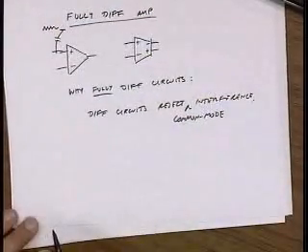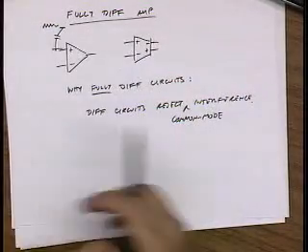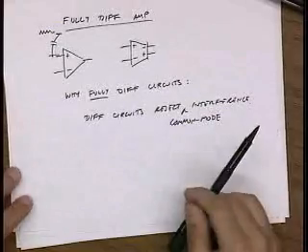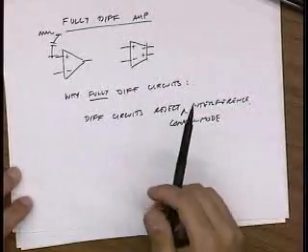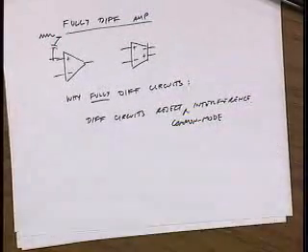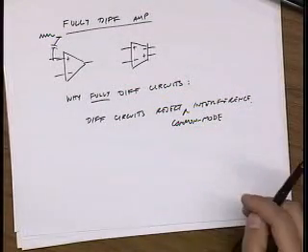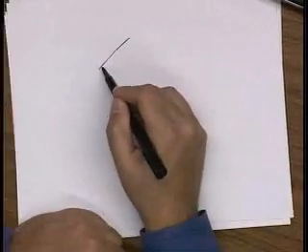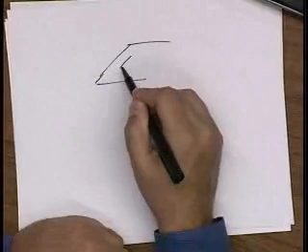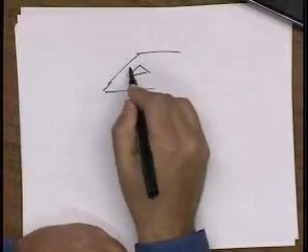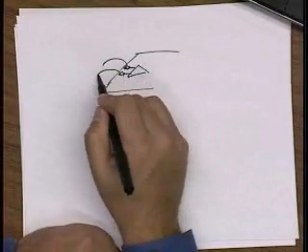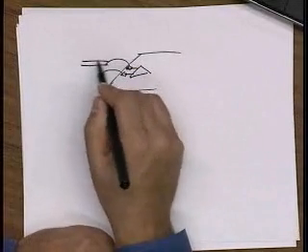interference. I said what kind of interference, and you said coupling, and then I said what kind? You said capacitive. Well, yeah, dominantly capacitive, but actually any kind of common mode interference is rejected, right? It doesn't have to be capacitive. Another example is package. So let's say I'm building an amplifier and I'm packaging it. And so I have these bonding pads, and then I have these bond wires that go to my package.